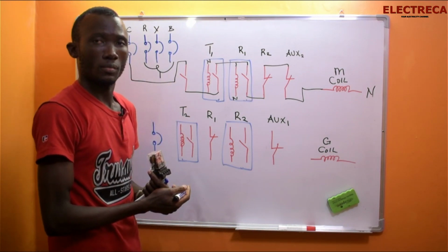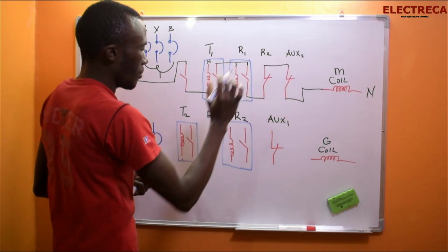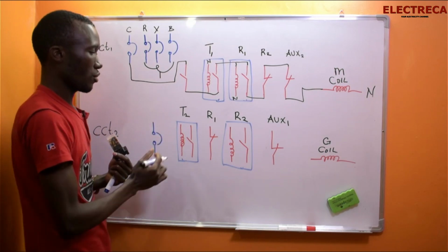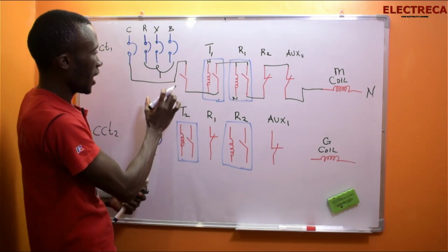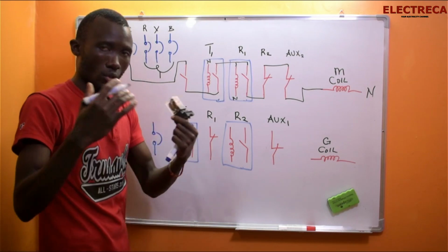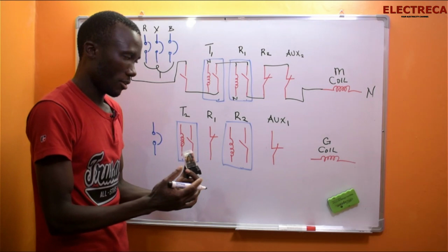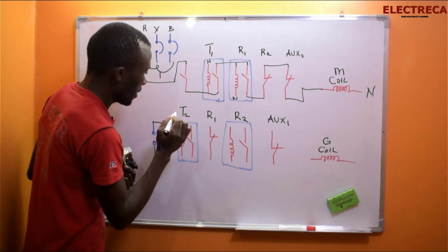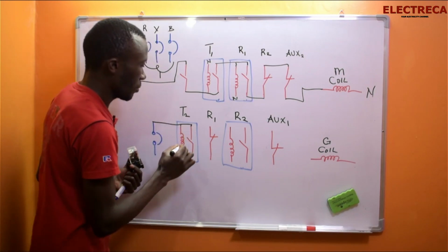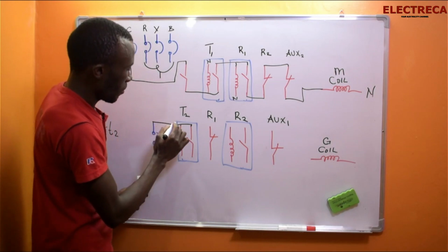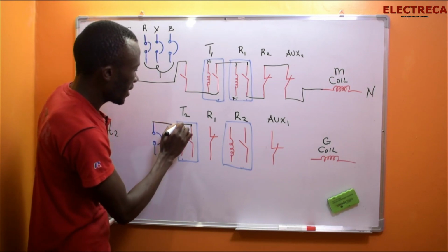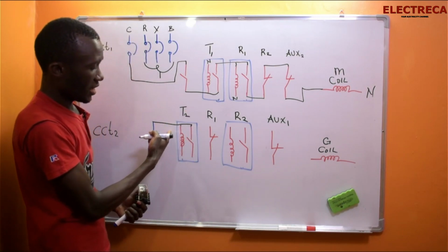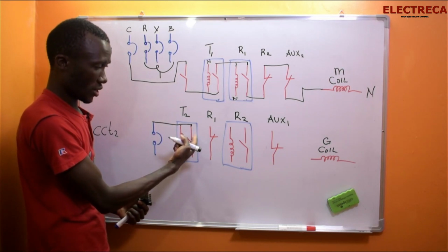All right? All right. Now, that's number 1. So if we come to the gen, we always have this breaker here, the control breaker. Now on the generator, you see that we don't have a phase monitor because all the supply that comes that side is clean, okay? So right here, we will just supply the relay, and from the relay, we supply the normally open of the, sorry about that. From this breaker here, we supply the timer of the gen, and then we supply also this contact here, such that when the relay is given power, it will close this, okay?